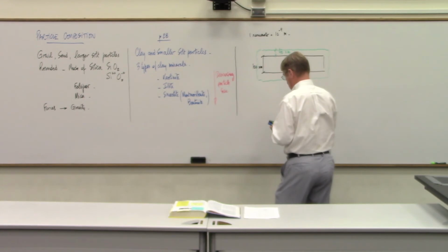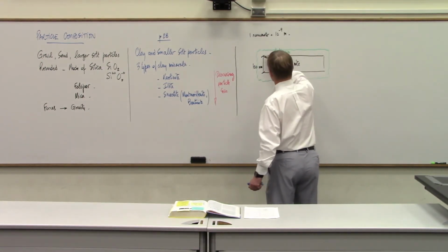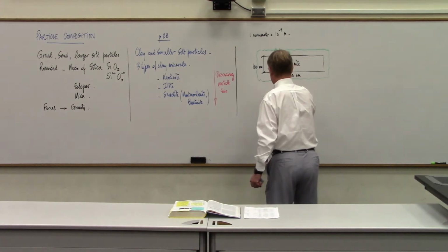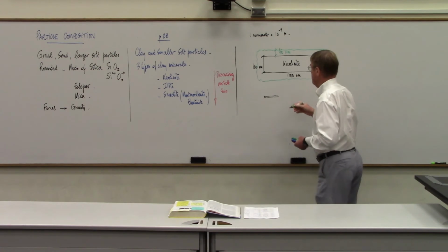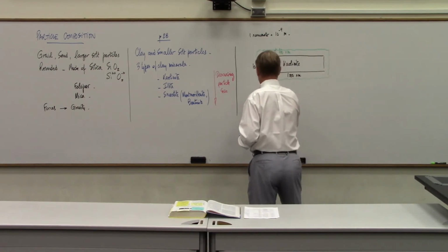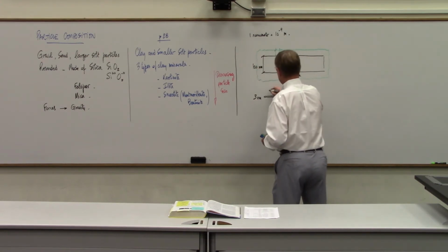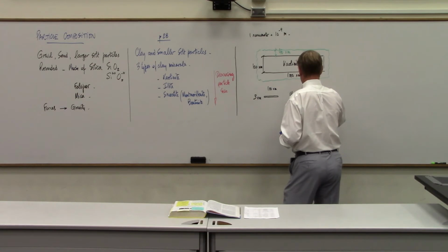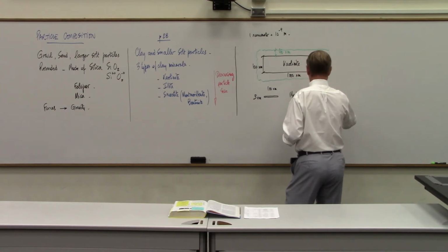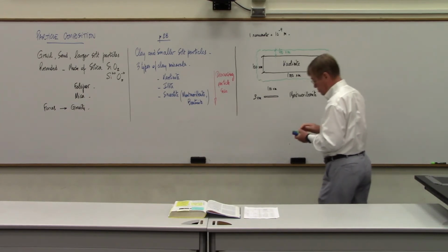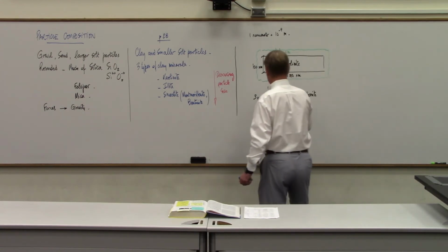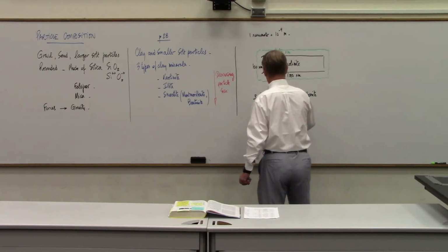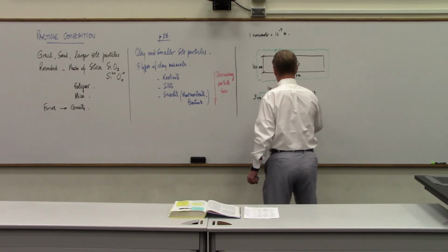Now, if I go to the Montmorillonite, for example, if I do it to scale, this is 100, this would be 3. I'm trying to do it not to scale, because obviously this is too big, but at least the relative scale of the two here. So this would be 3 nanometers. This would be about 100 nanometers. And here I'm doing the Montmorillonite particle. And it would be coated, again, by water attracted to it, maybe 20 nanometers or so of coating.